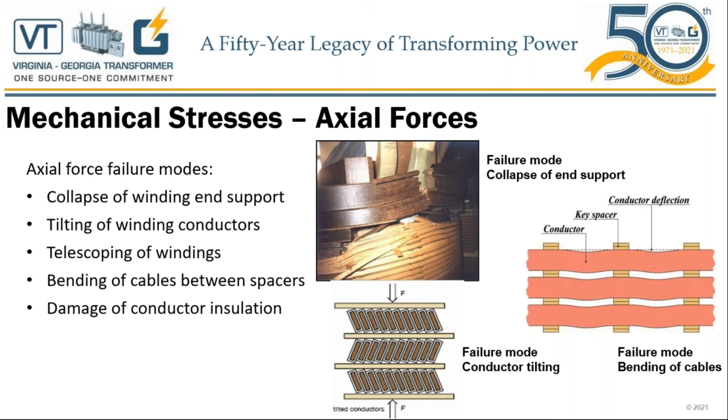No, maybe, but really the tilting may occur in this case if the winding has not been wound tightly. Telescoping of the windings, I spoke about that earlier, that the axial forces will try to push the outer winding upwards, which is what actually created in this picture the collapsing of the winding and support here, the pressure ring. Bending of the cables between spacers, that's the picture on the right side, and I actually have a real life picture coming up in the next slide. And of course, damaging of the conductor insulation.